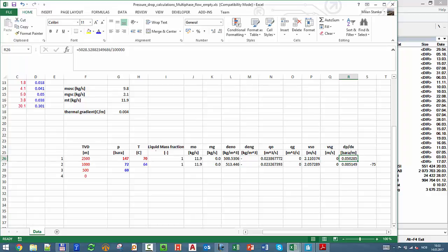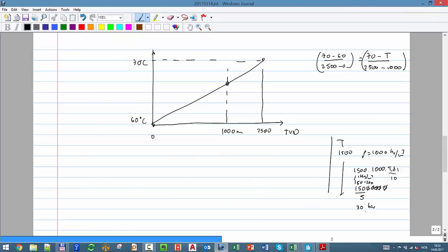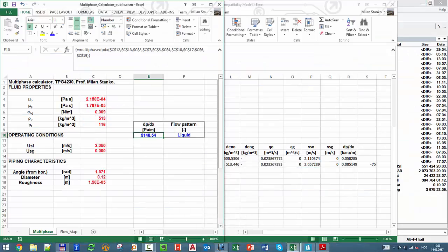I didn't do it, okay? I was trusting the model right away, and then I got exactly what I told you not to do at the beginning of this hour. You have to quality control, okay? So now it gives me how much? 75 bar, and pure water is supposed to give you 150, okay? So you say the density is like half. It makes sense, okay? With plus friction, plus acceleration, etc. But that number contains everything. This dpdx contains all the three components.